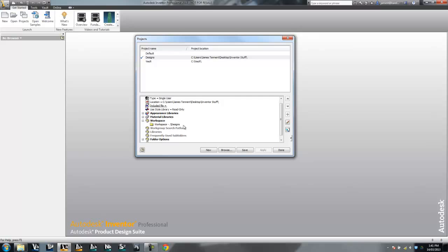And the way I'm setting this up is you can pick this up off the network, copy it anywhere you like, and it'll open up and resolve all your Inventor parts without a problem. Scrolling a little bit further down, you've got folder options, and here's the one that everyone misses, and I've had to clean up so many of these, it's not funny, so please be very, very careful. This one here has to be mapped somewhere communal.